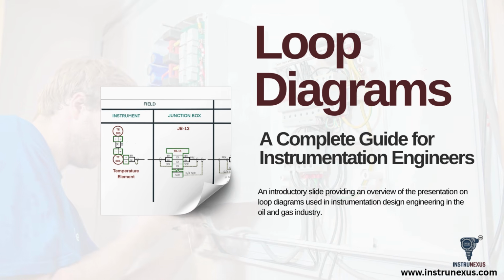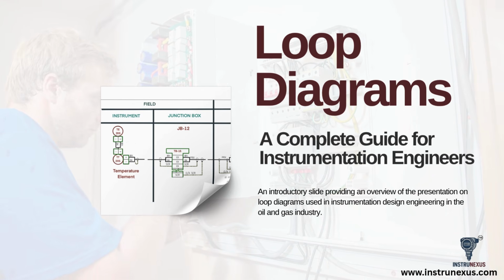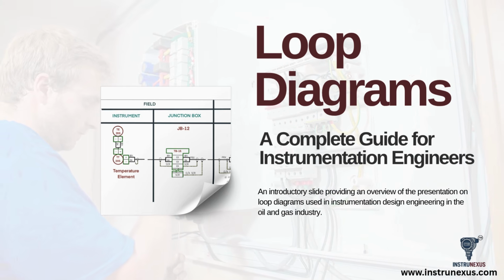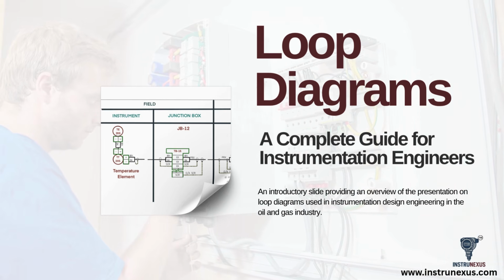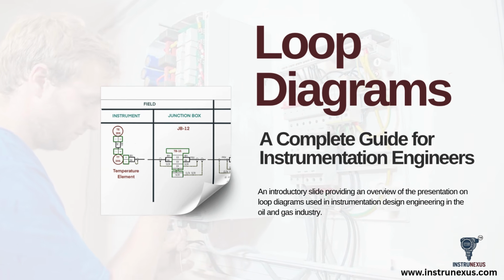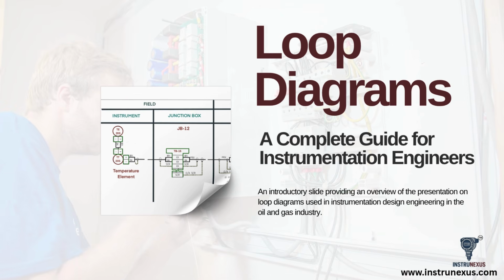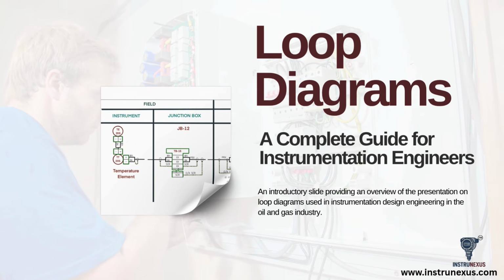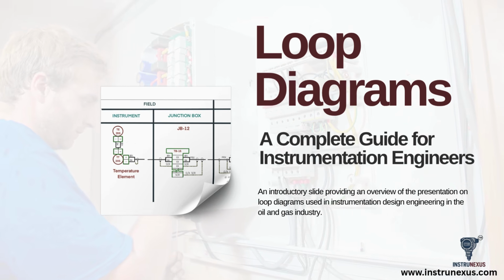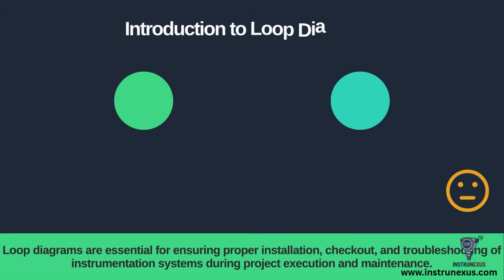They act as the essential bridge, connecting the high-level concepts you see on a P&ID to the detailed real-world wiring required for installation, commissioning, and maintenance. Over the next few minutes, we will cover this topic from start to finish. We'll explore what a loop diagram is, why it's so important, what elements it contains, and the standards that govern its creation. We will also walk through the step-by-step procedure for preparing one, look at common mistakes, and discuss its vital role during plant commissioning. Let's get started. So, what exactly is a loop diagram?